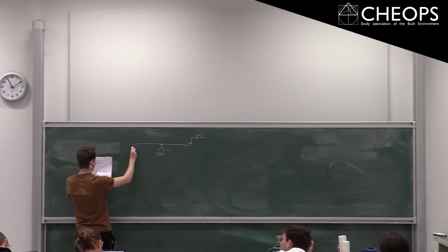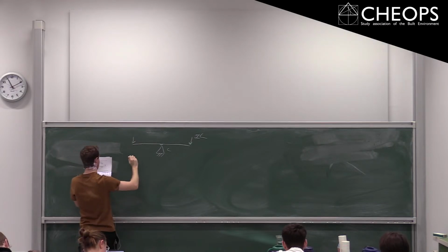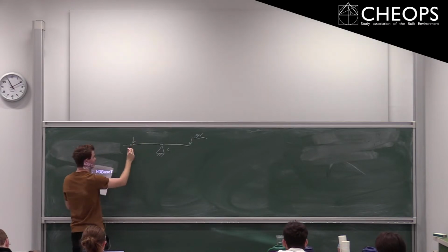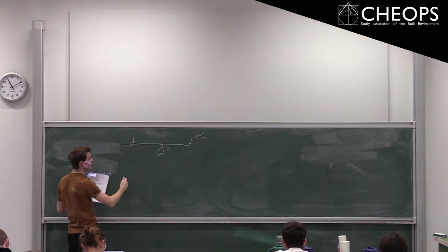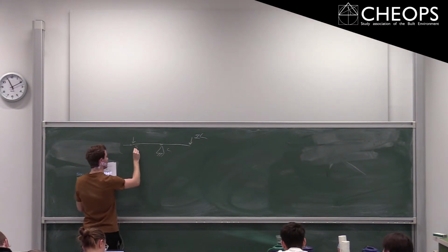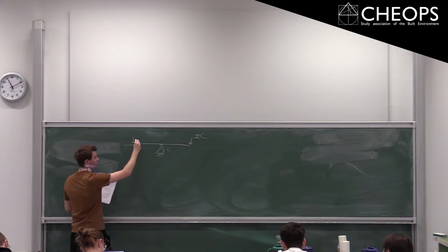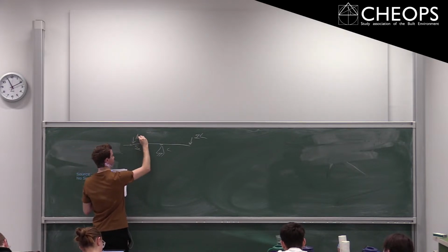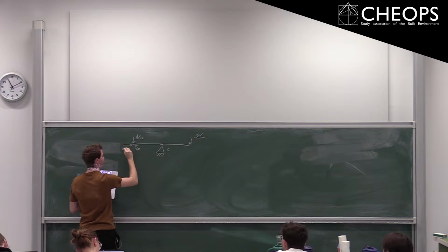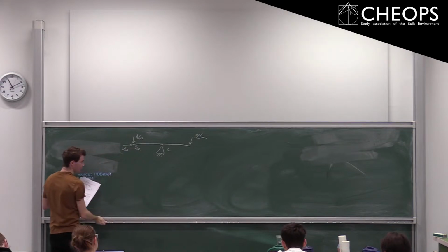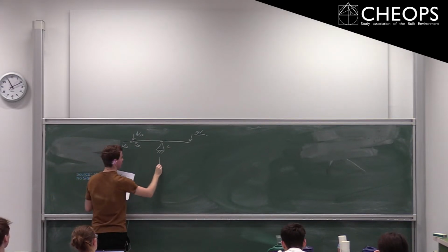And then we've got over here something is going on, right? These are internal forces because I just made a cut at this part, so that is S2. And there will be some, well, I'm going to call it a normal force because it's in member S2, and the shear force of that member. And we know here you've got two reaction forces, right?